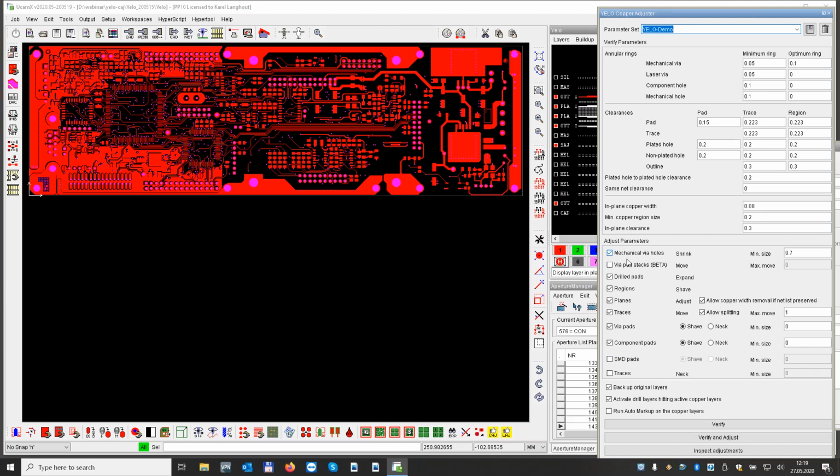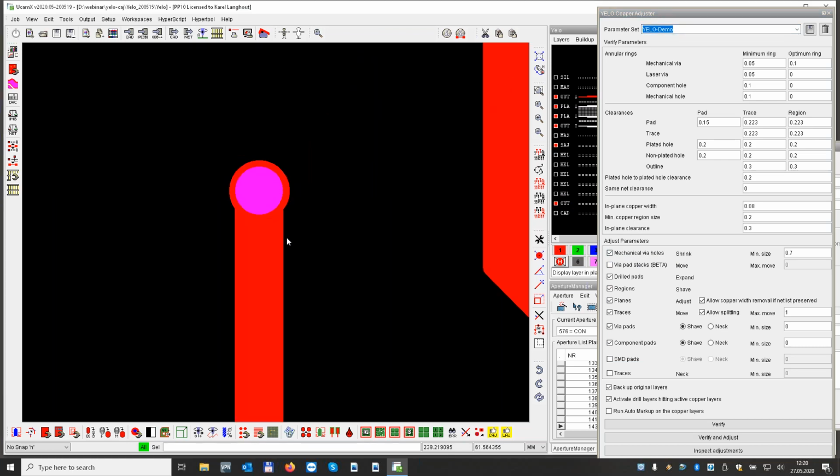Okay, so we have something like here, the mechanical holes. If I actually look at my data, for example, at this position, I have a hole and I have some copper. Now, interestingly enough, if I put my original drill layer on top, you can see that my original drill layer, which is now kind of a sandish color, is a little bit bigger than the hole that I have now. So it actually made the hole slightly smaller.